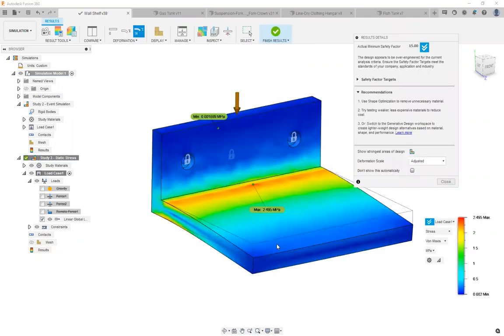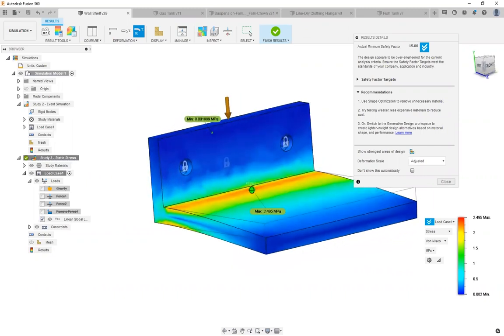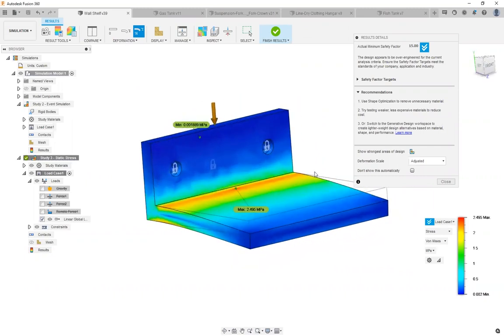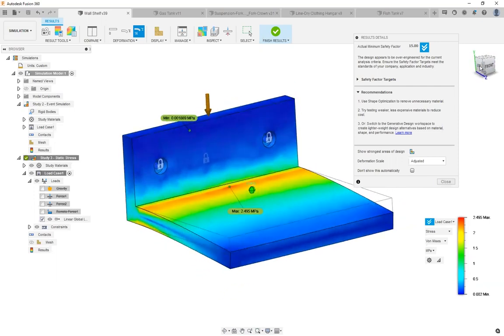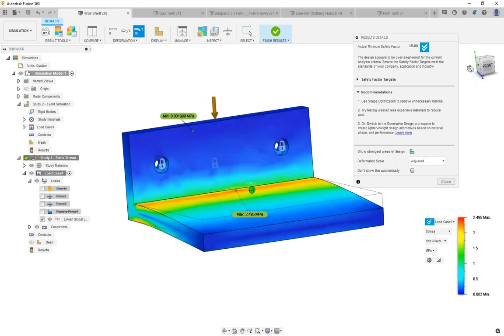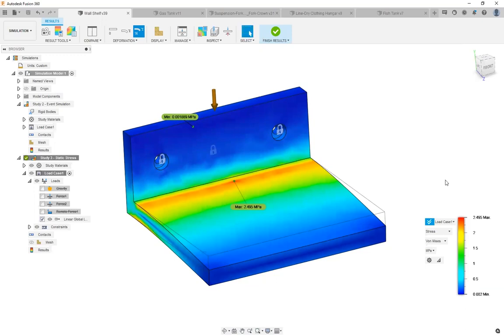As you can see, it affected this part of the model as well. And that's because, again, it's towards the entire mass of the object. And if there's no mass in here, then it's not going to work at all. So that's why it's bending here, because this is the only part that's fixed and everything else is susceptible to the acceleration that I applied to it. That's my best representation of explaining a linear global load. Do what you will with that, but I figured it'd be nice to at least mention in this segment.